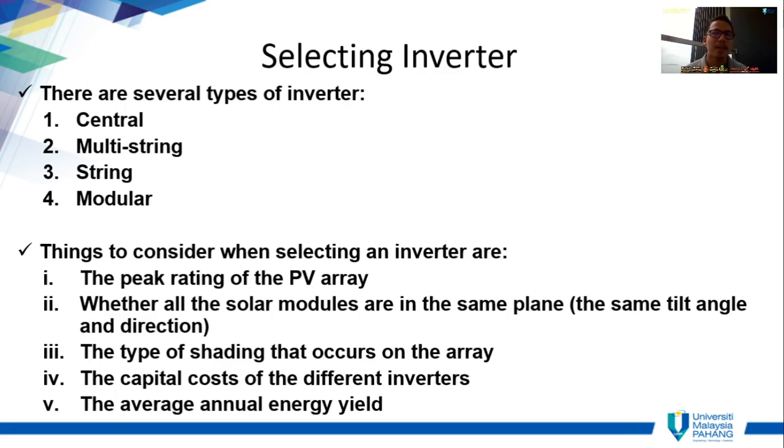During the site survey, we should already know whether shadow exists on our modules throughout the day from 7 a.m. to 7 p.m. If there are some shadows that we cannot avoid, but they are less than 5%, 10%, very little, maybe we can still consider installing without worrying.